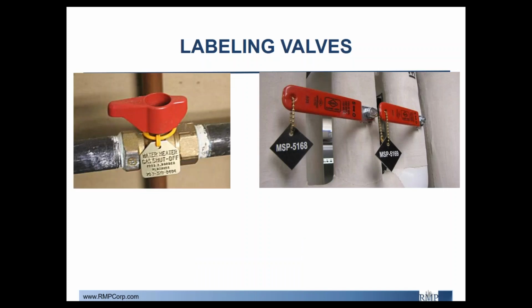For valves, it's a little bit easier to label. Obviously, you can use dog tags, stickers. It's a little bit more accessible in a way, and valves are actually probably more important than pipes because, at least for me personally, when I'm walking down a system, valves represent points in a line that are easiest to identify. Now that becomes complicated if you're looking at a system where there are 25 valves in parallel and you're trying to figure out what line belongs to which without any labels. So labeling valves is very helpful for any engineer that's walking down the system, and it helps them do a sanity check when they're walking down the system.